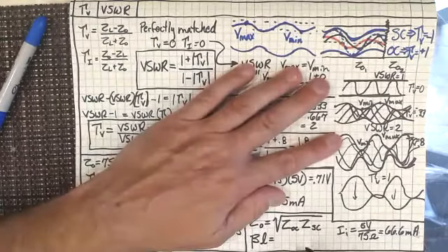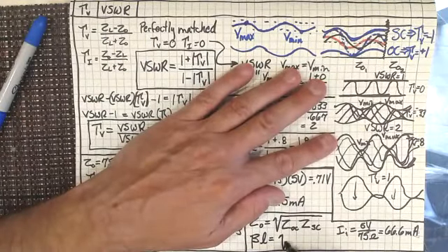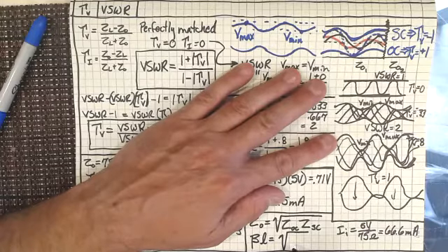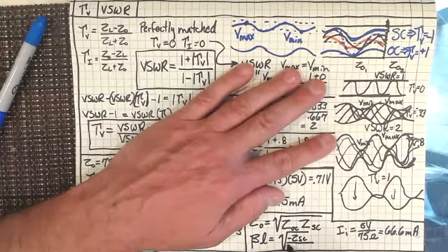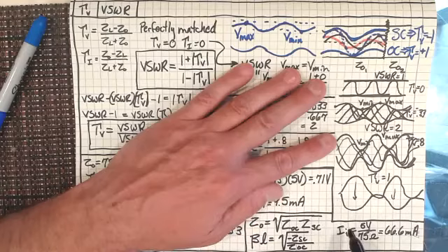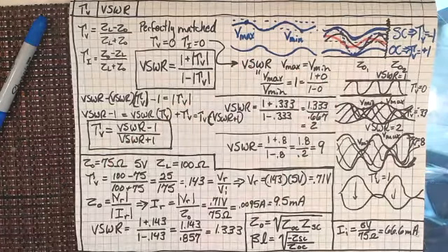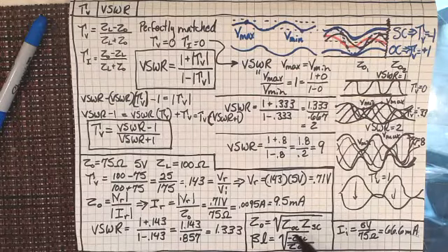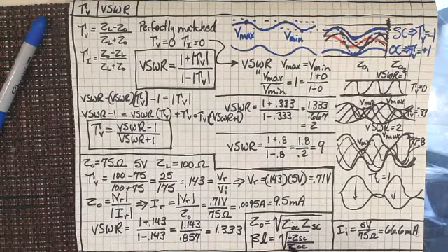I just want to point this out. So this is going to be the square root of minus the short circuit impedance divided by the open circuit impedance. Now your book has a really good example; that's further along, I think it's up to 8.7, 8.8, something like that. It has a very good example of how you would use these two identities. If you knew what the open circuit impedance was and the short circuit impedance was for a line,